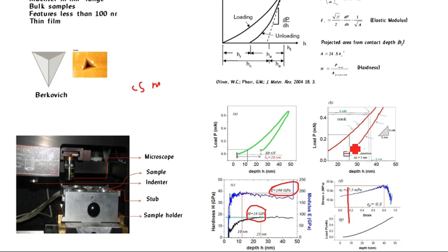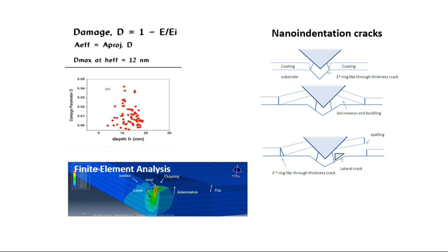So these are basically the shallow cracks that get developed on the surface. So this can represent the different sorts of cracks. Again, the damage and fracture of these coatings were studied. Now, there's a difference between damage and fracture. The damage is the one which is due to an enhanced plastic deformation.